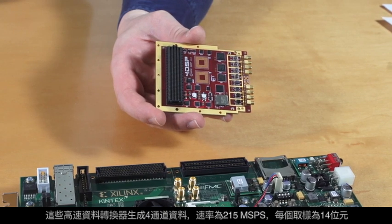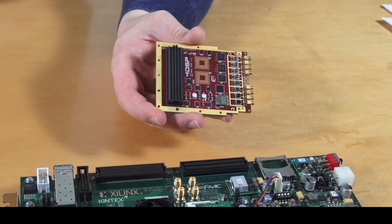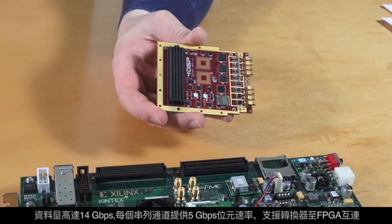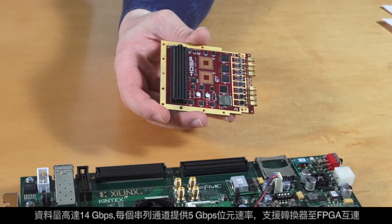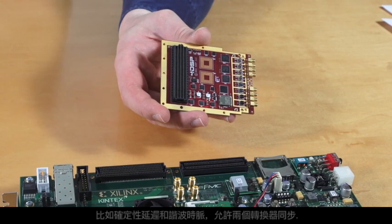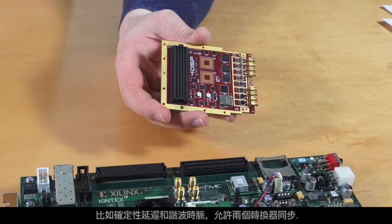These high-speed data converters generate 4 channels of 250 megasamples per second at 14 bits per sample, a whopping 14 gigabits per second of data. By providing 5 gigabits per second bit rates per serial lane to support the converter to FPGA interconnect, it takes the minimum number of lanes to transfer that data, as well as providing additional valuable functions such as deterministic latency and harmonic clocking, allowing the 2 different converters to be synchronized.